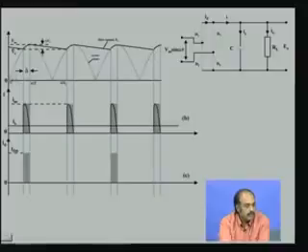This rectified sine wave is what you would obtain here, as I am showing with the mouse pointer, and only during this portion there is conduction. Therefore, the currents of the diodes would be of this nature, sharp, and there are no currents at any of these other points.